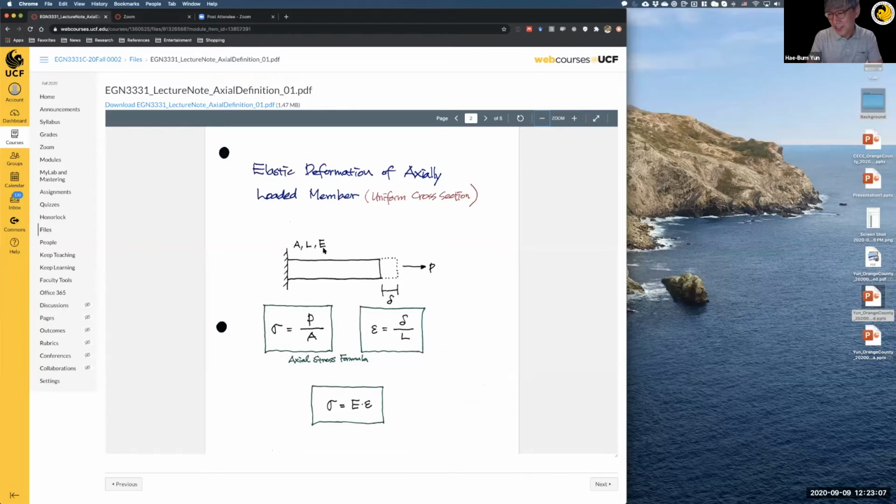Are you sure, guys? Again, modulus of elasticity, larger E. Jen is correct. Larger E: when we have a rigid or stiff member, we have a larger E. So Young's modulus is a material property to measure the stiffness. Okay, so steel is stiffer than rubber. That's why the steel has a larger E.